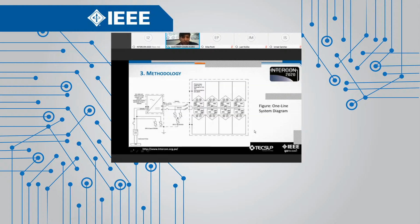In this figure, we can see the configuration we have installed with this type of technology. We can see the DC and AC protection shield for the solar inverter, and each photovoltaic panel has its DC-DC converter.